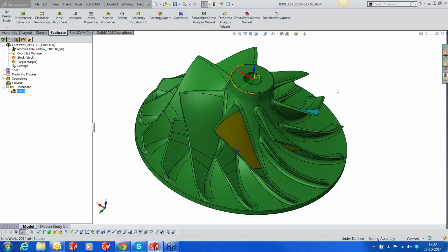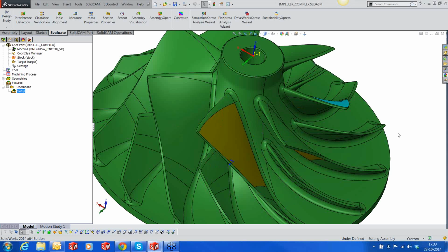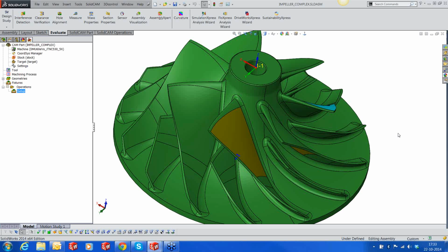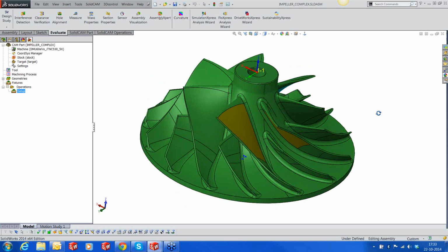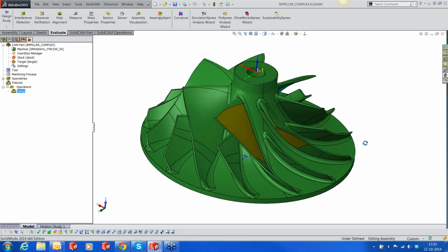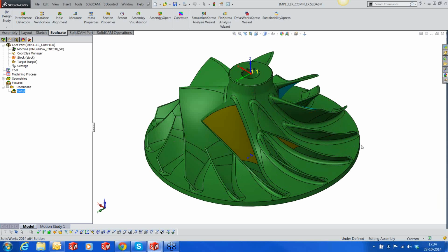In many of the times that we're cutting an impeller or we're doing a 5-axis, the fillet plays a very crucial role because it can really make the programming of 5-axis parts very, very tough when you have a fillet at the bottom. Now, in the Multiblade application, we even handle fillets. We handle fillets which are constant in nature. We also handle fillets that are variable, like, for example, this particular fillet that we have. It's basically a variable fillet that we have.